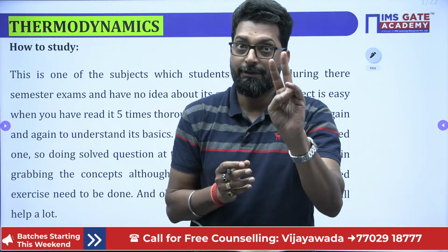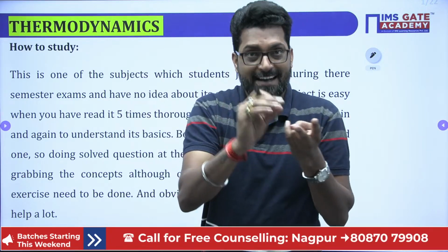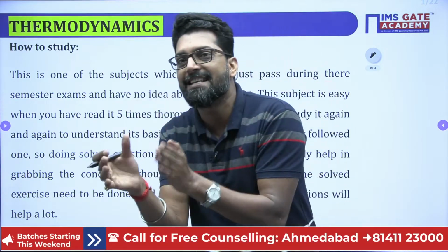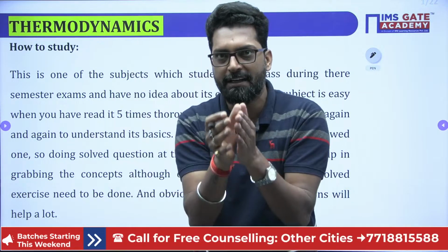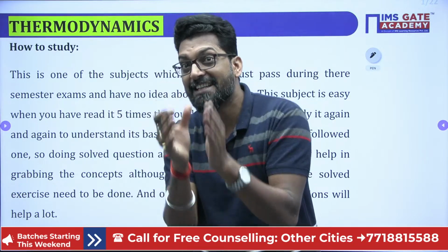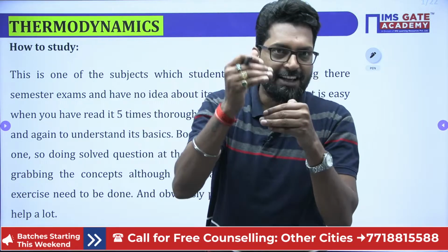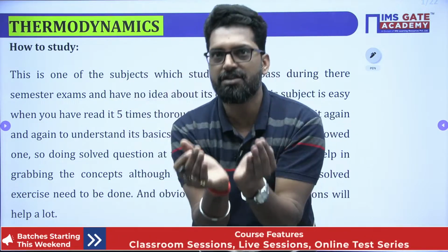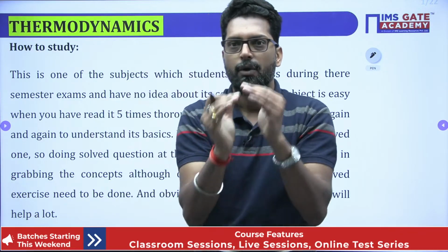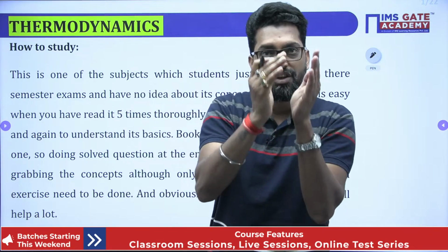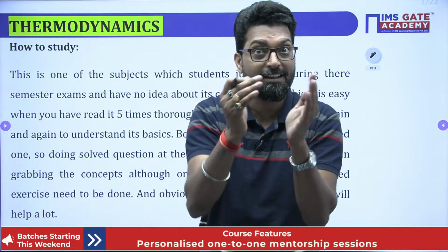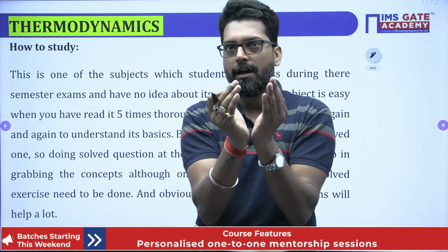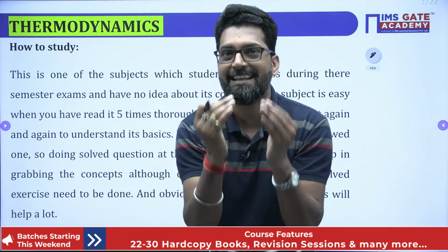One thing is very clear: work transfer and work change. The flow work will change, it is not transferred, because it is a property. But boundary work will not change, it will transfer. The transfer term is associated with the boundary phenomenon, while the change term is associated with the system property. A system always changes, so the quantity associated with the system is your property.